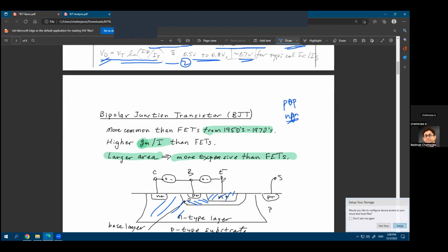Remember that we said that during saturation, from the source there is an influx of carriers, right? The source will create a lot of carriers, and they will pass through the channel and be available at the drain. So remember that in saturation in MOSFETs, the channel is pinched off, so the channel does not exist fully between the source and the drain.